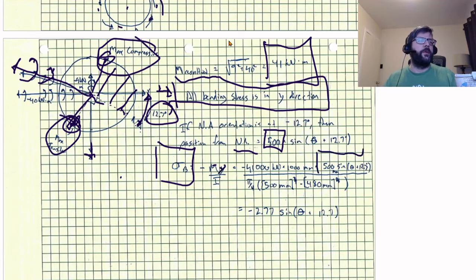So here's the term we had for the y, and here's our moment in terms of newtons. Oh, sorry, I realized that should say newtons right there. I threw in an extra 1,000 so I could say newtons instead of kilonewtons, but I accidentally drew the kilonewtons. So everything here is in terms of newtons and millimeters, so that I can get a nice megapascal answer when we're done.